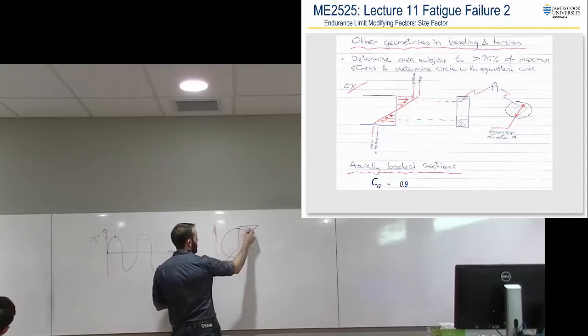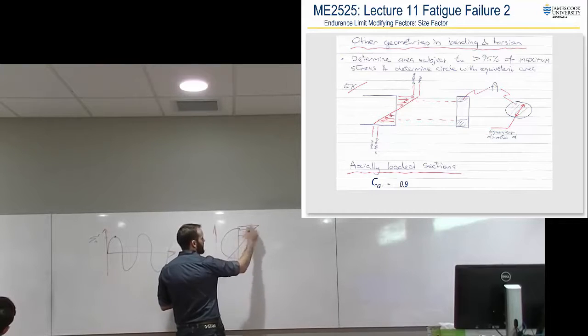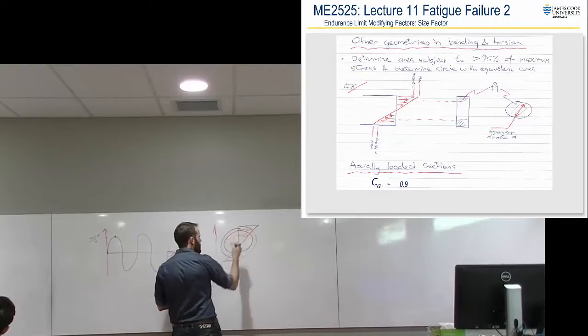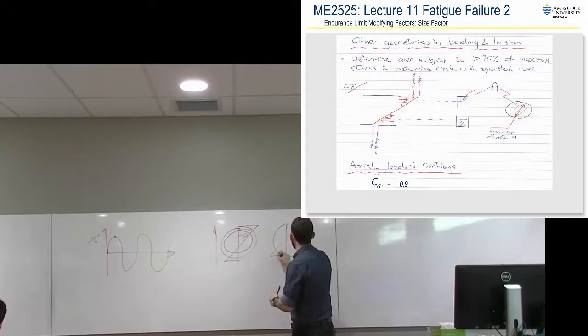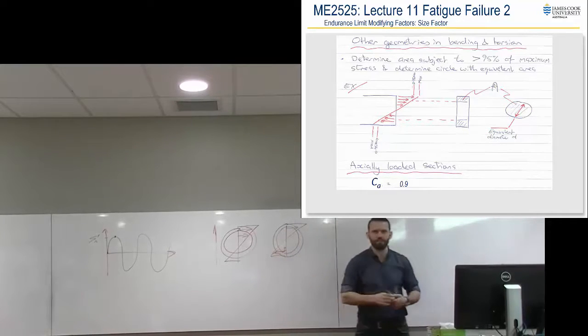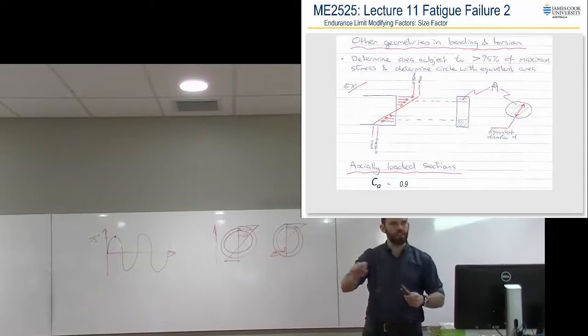Technically into the page. So we have our maximum out here, but if it's rotating, it's that maximum that goes all the way around there. And if you think about torsion, it's exactly the same. Torsion, the profile's like that, except it goes the other way. And once again, it's that outside sort of 5% that is going to be critical.